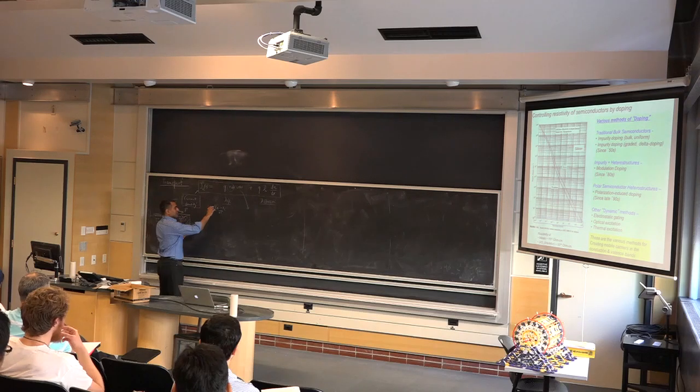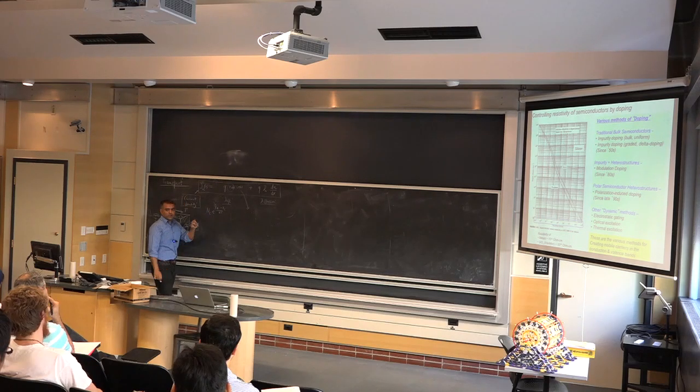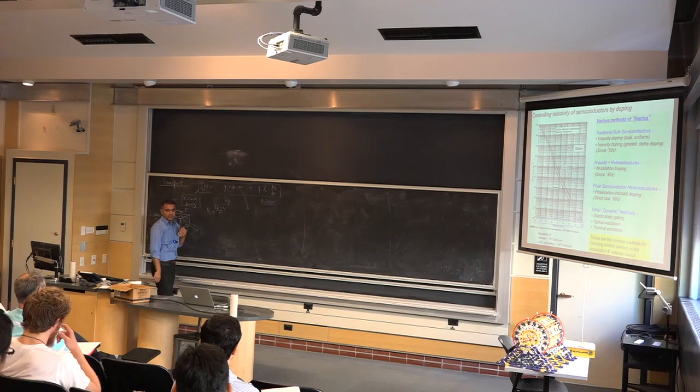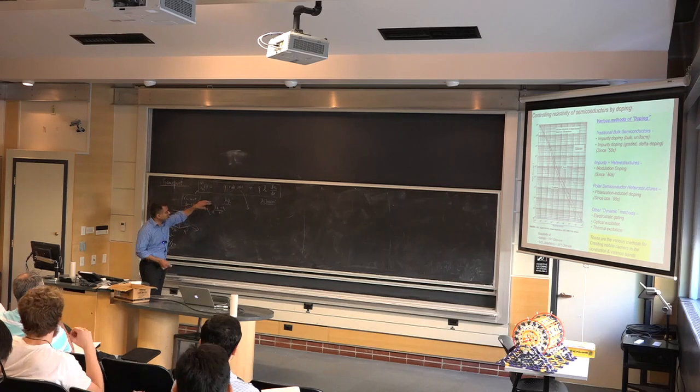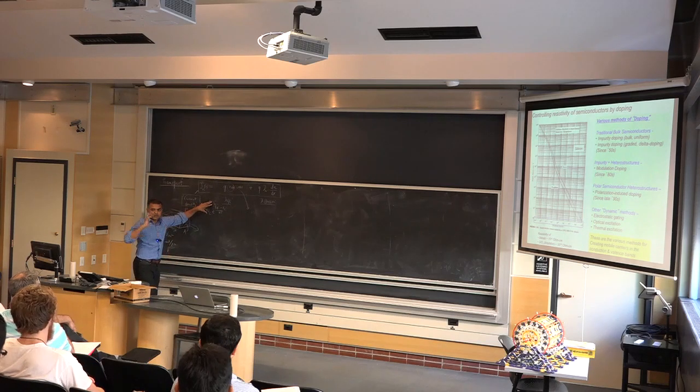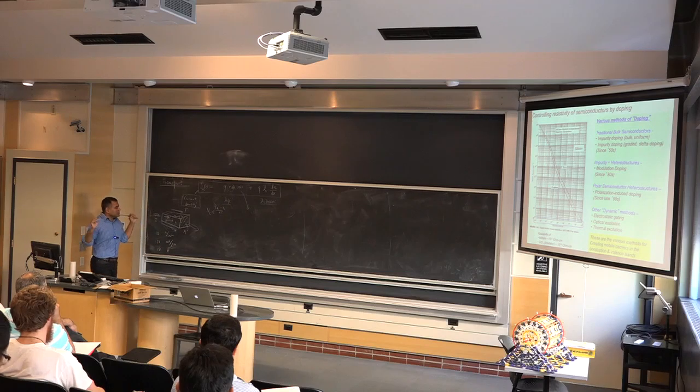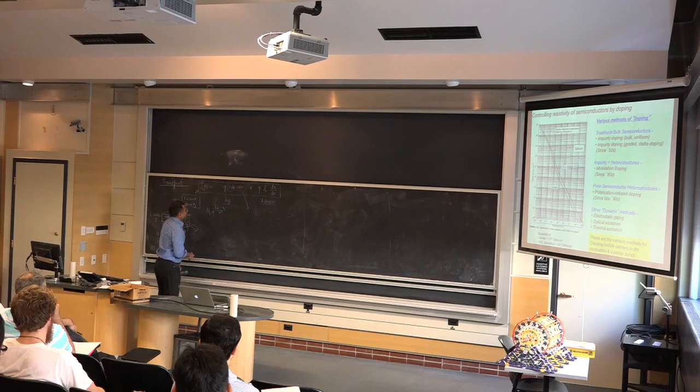We are going to change this to what we call a quasi-Fermi level. The moment I pull it out of equilibrium, there is no one Fermi level in the material. So we are going to change it to the quasi-Fermi level. The moment you do that, this formula is still valid. So we're going to distort the concept of Fermi level to make this formula work, right? Okay, good point.